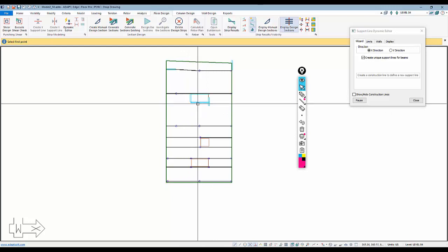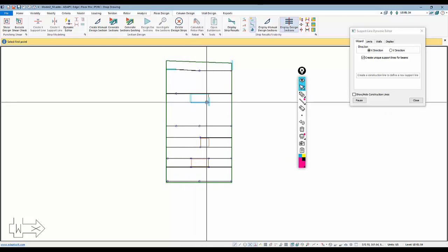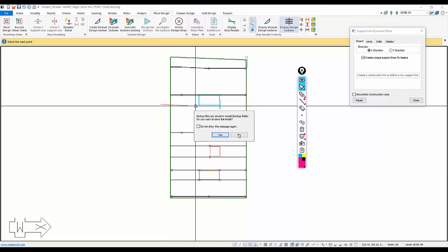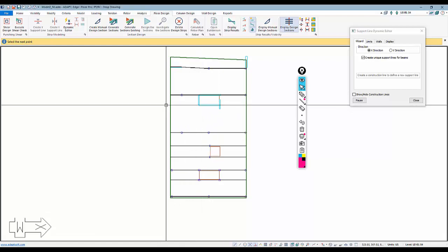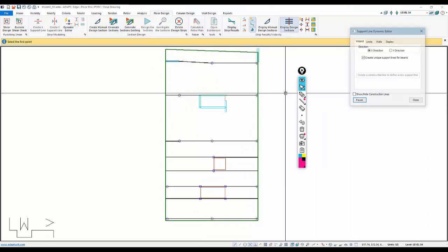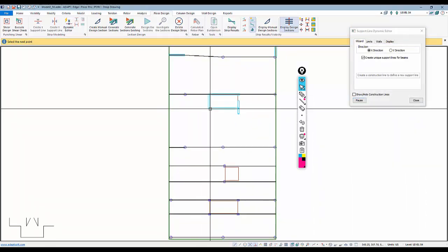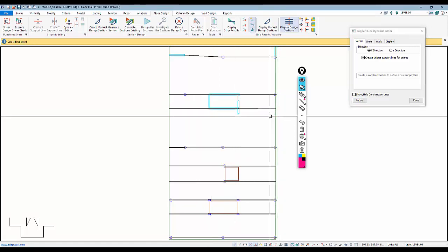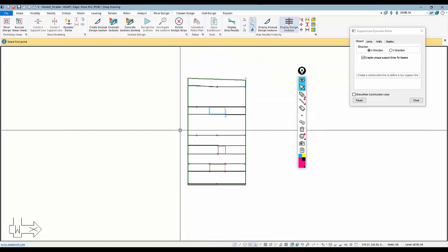I also want to do this at this wall. This is clearly a support for the slab, so I'll just click out here. Go ahead and say no to that. Let me try that again. Let me reopen that. So coming back to this, I'll select the option to where I click near the endpoints of the wall and then enter to close. So those are the strips for the X direction.